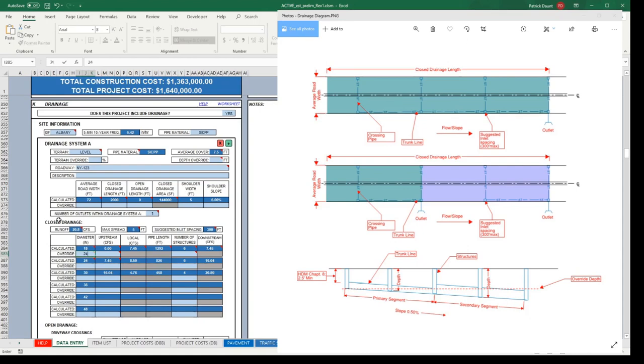Put 24 in, and you'll see that this upstream value populates. This upstream value is equal to the next lowest pipe diameter, as if it was flowing full. So this is basically an 18 inch full flow pipe coming into a 24 inch pipe, and the rest of these calculations are based off that assumption, so all the flows are injected with that assumption.